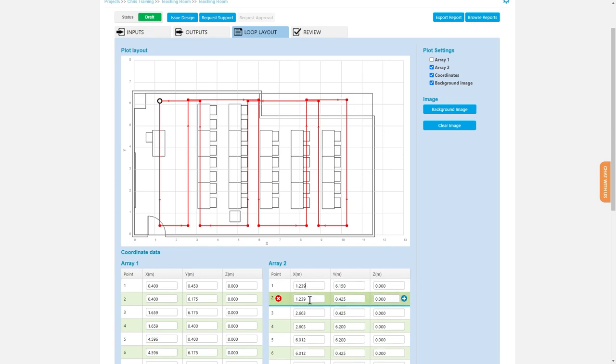You might notice that the points move around in a slightly unusual order. You can see the arrows and the points follow the direction of the current flow. Due to these crossovers, which are critical to the functioning of a hearing loop system, we sometimes skip past a loop segment and go to the next one. The easiest thing, therefore, is to have a look at the grid and find the rough dimensions that you're looking for, and then identify that point in the table below.